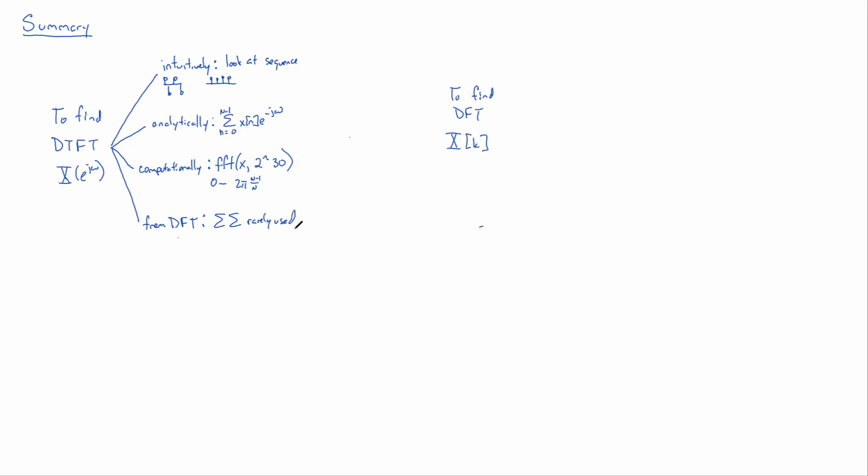And that's because in practice, if you have an output signal that is not smoothly sampled, that looks like this, and if you put that signal into a speaker, that speaker's got a voice coil, and that voice coil has inertia. And that inertia is going to smooth down the response to make it smooth.